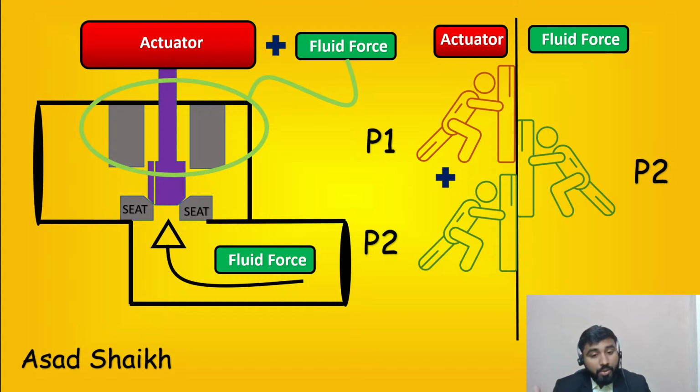Recommend to your client or your original OEM that a control valve's inherent capacity is to control, not to shut off.